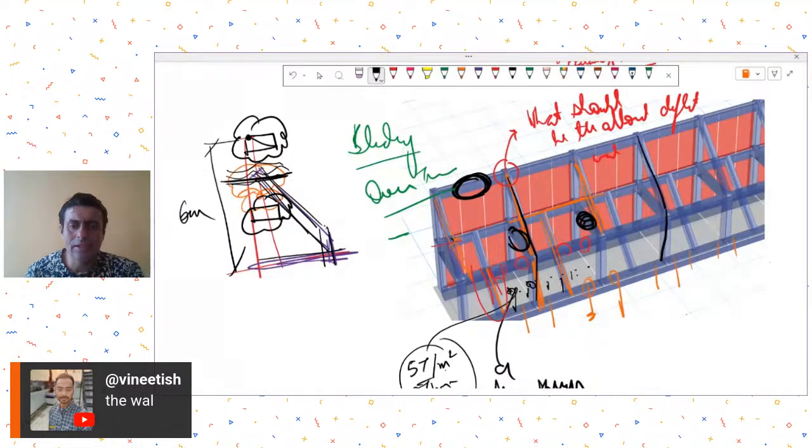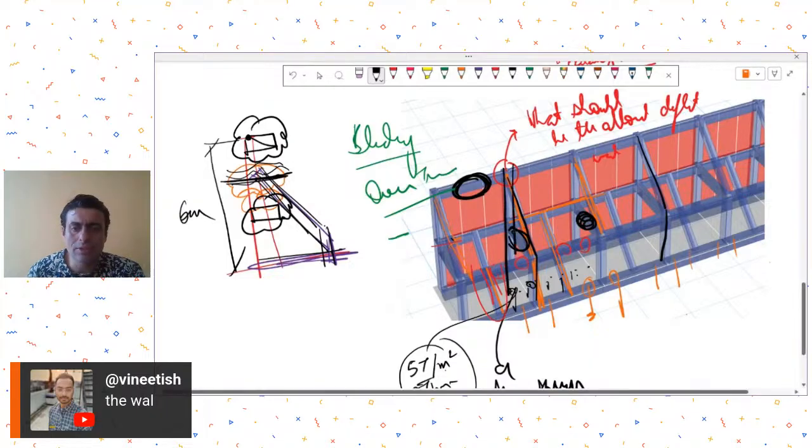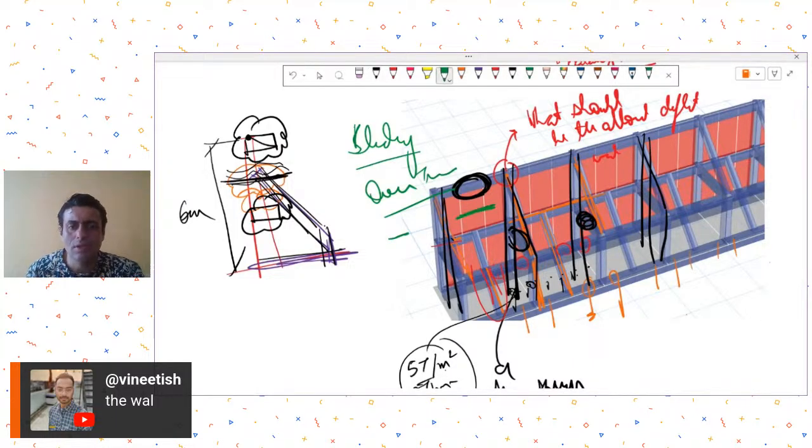And I still think you can try it out. Maybe if you give just one system like this, something like a counterfort, and have it stiff enough so that your walls get major bending in this direction. Try to have it like this. For that, you may have to stiffen up this system over here, the vertical frame.